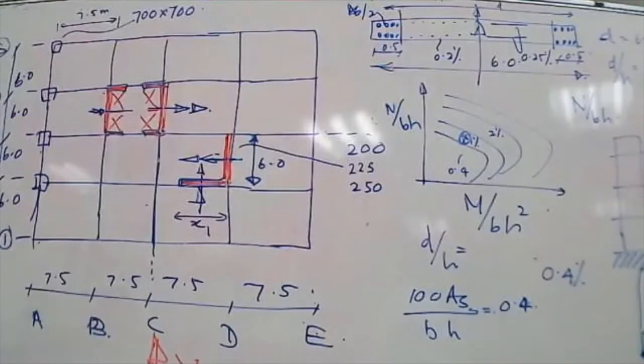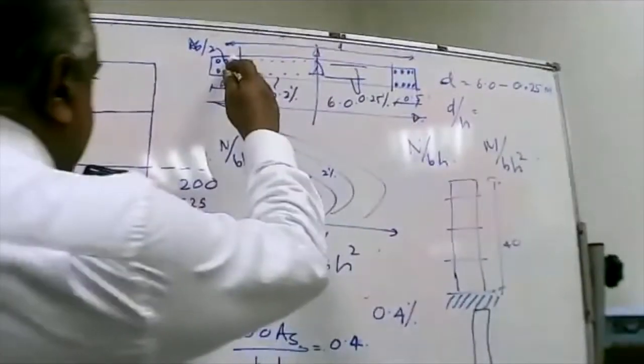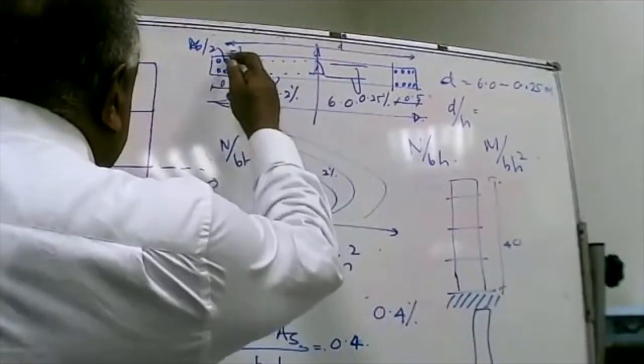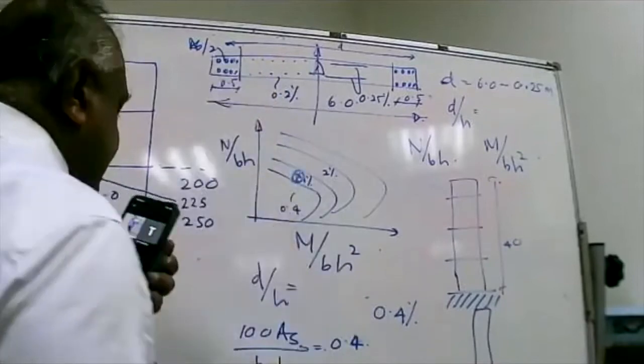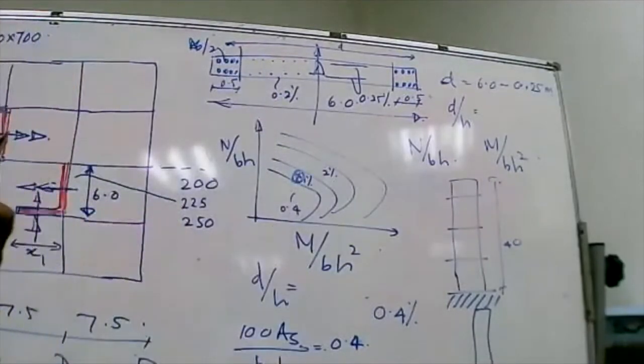No. For wall reinforcement, that concept will be applicable if the amount of reinforcement in that particular area is more than 2%. So we calculate this concentrated reinforcement, then calculate the amount of reinforcement in this particular area. If it is more than 2%, then you have to ensure that you detail it exactly as a column.